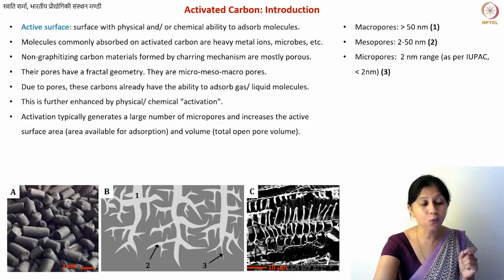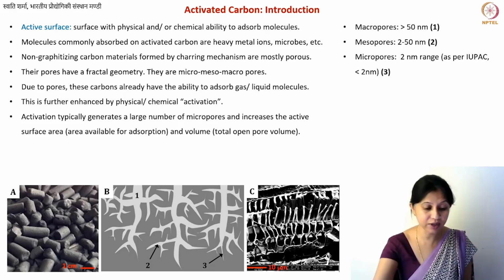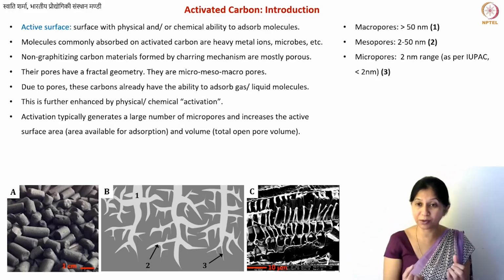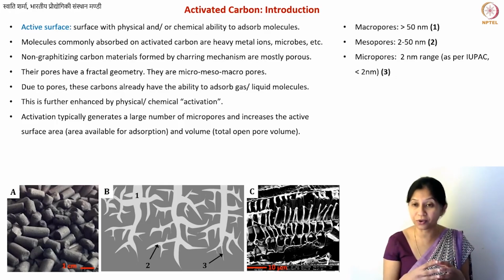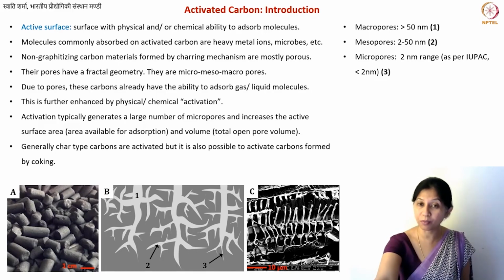Okay. Now, what is important for us is the surface area that is available, because you see, now we are doing adsorption. So the more surface area available to us, the better. That becomes an important parameter, along with the total open pore volume. If you have closed pores, they are not useful for you. So these are the two important factors. Now we need to increase these two things: we need to increase the surface area, and we need to increase the open pore volume.